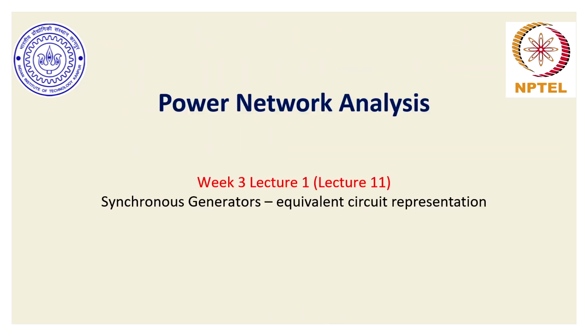So in today's discussion, we will build on the discussions from the previous lecture and try to understand how the electrical equivalent circuit of a typical cylindrical pole synchronous generator would look. What are the governing equations in phasor domain that help in understanding the steady state behavior of a synchronous generator.